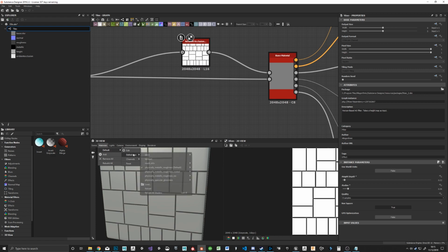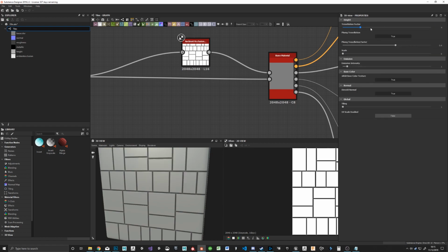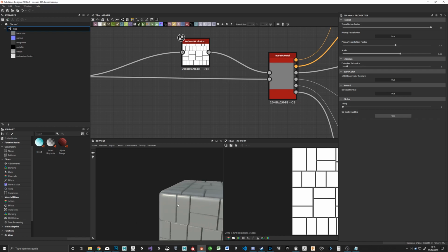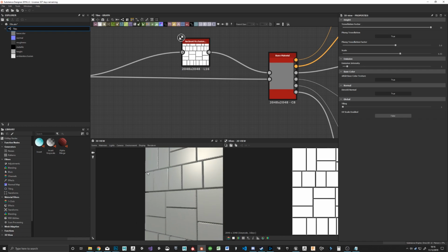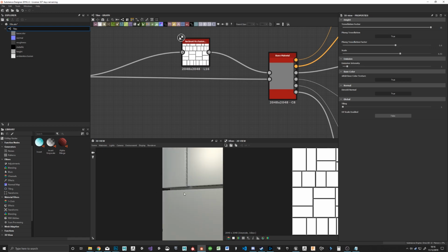The other thing I want you to check out is the materials. If you go to default definitions, we're by default sitting on the physically based material roughness. Now there's two options. There's parallax occlusion, and that's essentially taking the geometry we have and using a texture to fake a transition of parallax. Tessellation actually takes your geometry, multiplies its tessellation factor, and then actually physically protrudes out your surface. So you can see how I've got these little cutouts. The silhouette is actually being geometry cut from my surface.